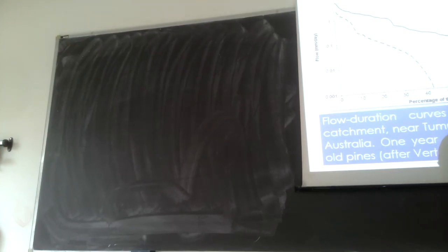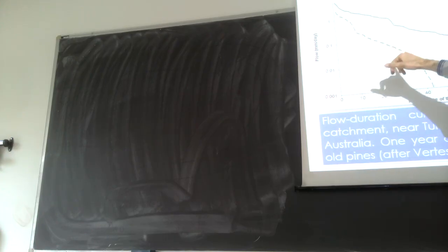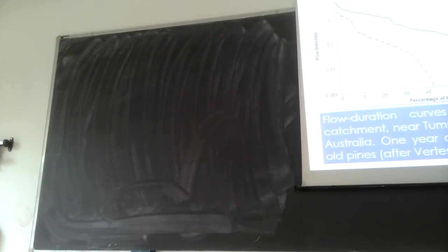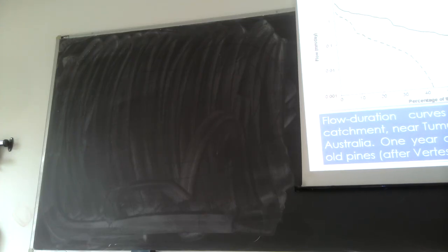Pine trees have grown, their root system went down deep into the soil, okay? Interacting more effectively with groundwater, enhancing, increasing the evapotranspiration fluxes. As a result, during summertime, low flow season, the water that normally fed the river from groundwater flow when the slopes were pastures and fields is not available any longer because the pine trees are using it.